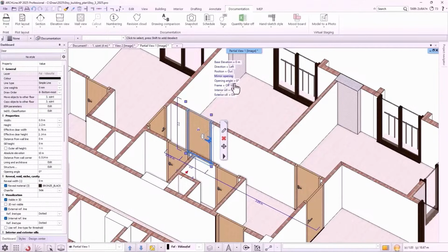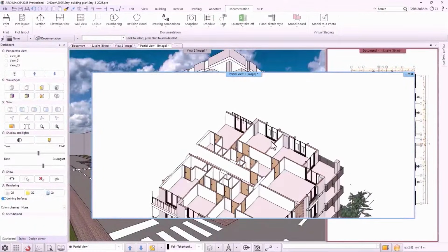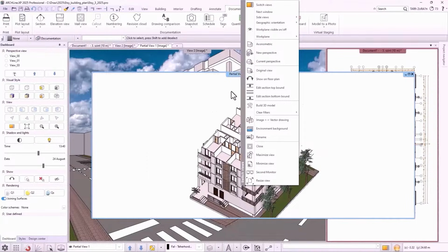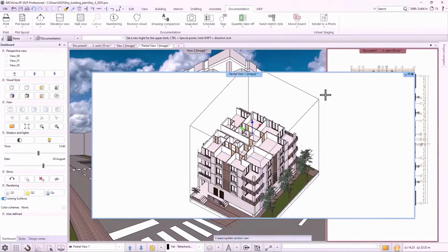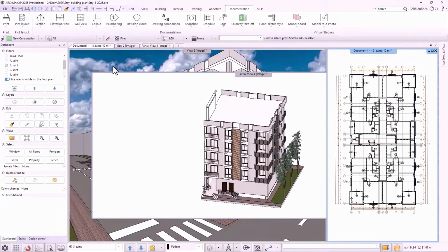This is a useful feature if you want to quickly change the 3D representation of the building or access hidden parts of the 3D model. If you want to reach another part of the building, you can move the boundary anytime. If you want to set the original top boundary height, activate the command again and move the boundary plane to the top.